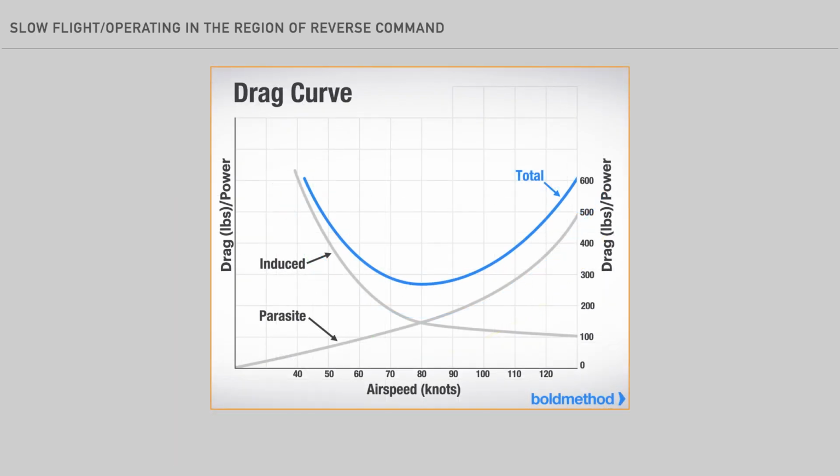Now suppose you are flying along trimmed for level flight on the front side of the power curve, and a wind gust caused the nose to pitch up. What would happen? Well, the airplane would momentarily slow down, but if there was no change in the power setting, would it return to its original speed?